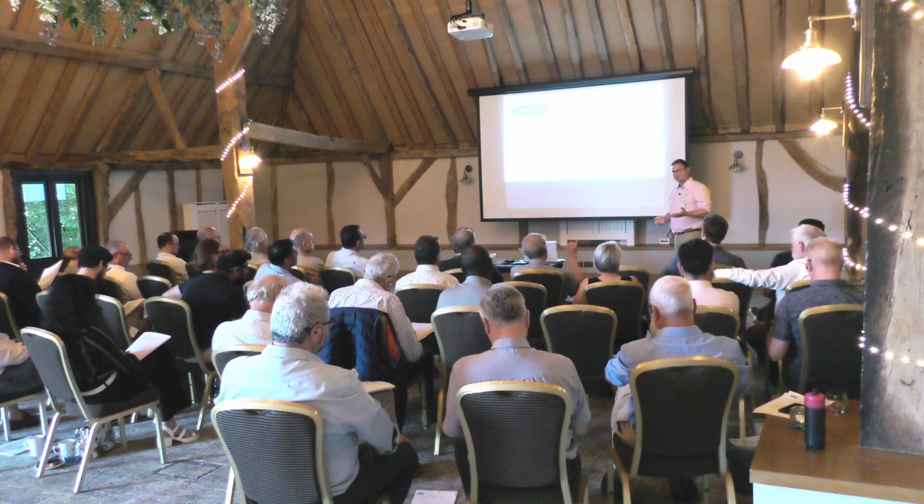So the two options that you have in ADB is that you should have a full escape route, protected corridor, top to bottom, FD20/30 doors with fire-resistant construction, 30 minutes. That's it, with circulation spaces alarmed in accordance with... You've got no gap between the bedroom and that door on the first floor.